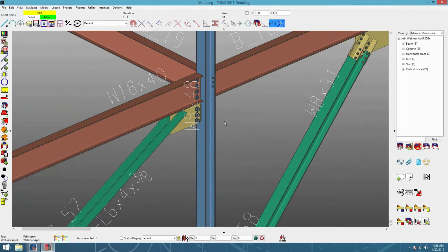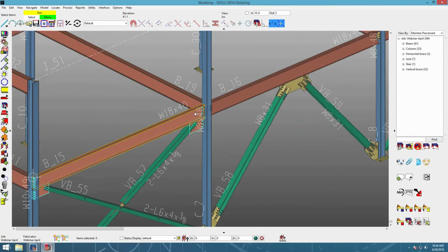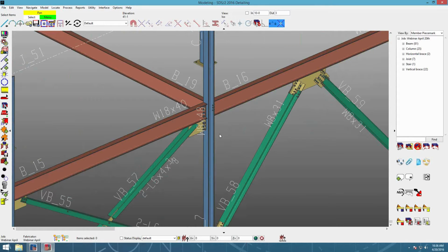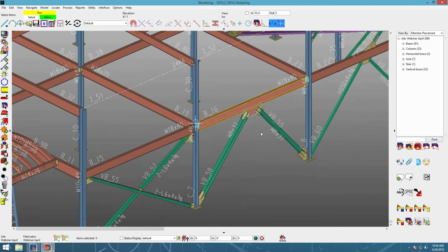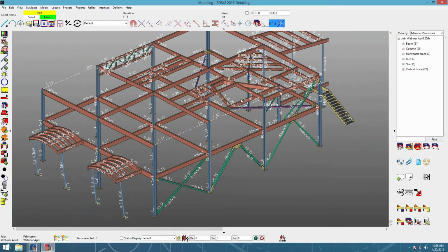Now, you can turn off parts of this automatic process and create solids. The processing of the members happens as soon as you say OK. There's nothing to turn that off. That's just going to mark it for processing as soon as you make the change. The regenerating of solids and the create solids routine that does all the piece marking as well can be turned off so that you can process everything at once if you don't want to continuously update the solids and everything